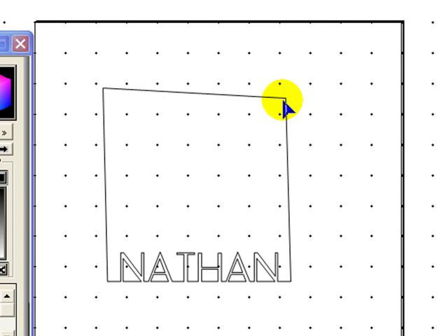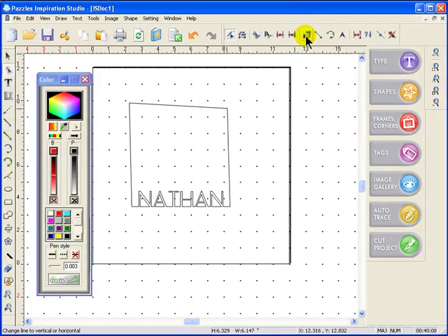There is actually a marvellous tool which will help you out with this. Up on the move toolbar there is this vertical and horizontal bar. It basically straightens your lines, makes life so much simpler for you. So if you click on that, come down to the line that you want to straighten, click on that, can you see it's automatically straightened it?